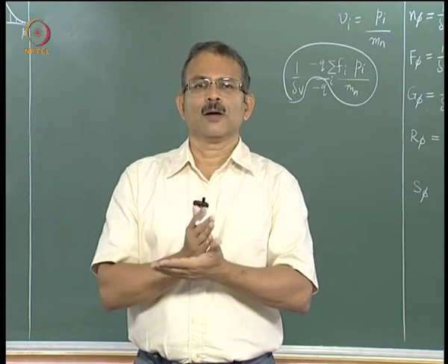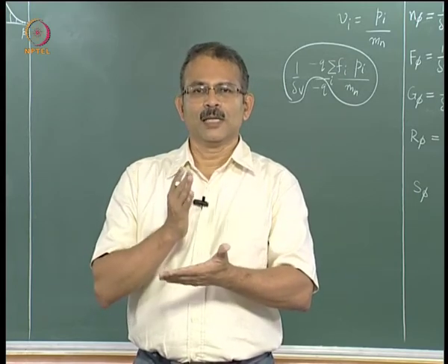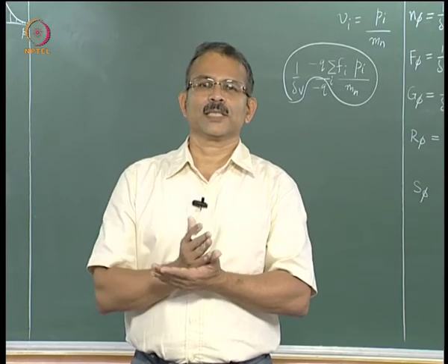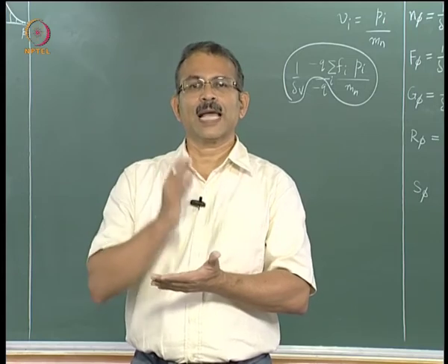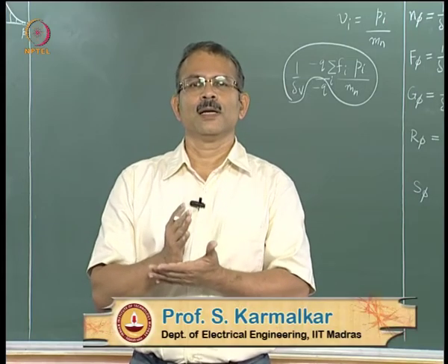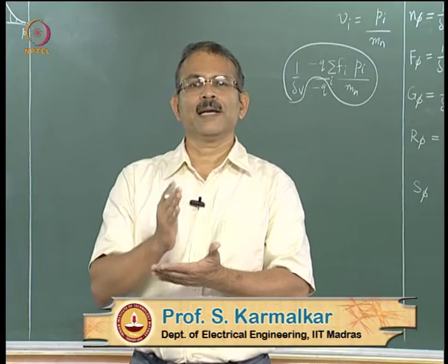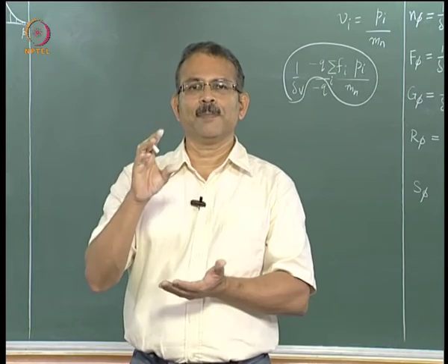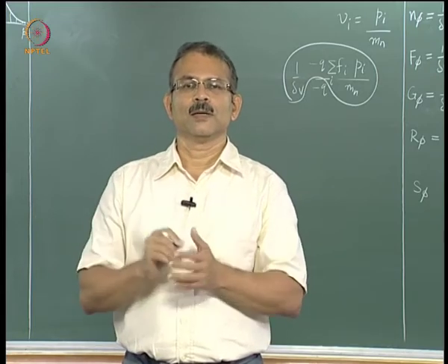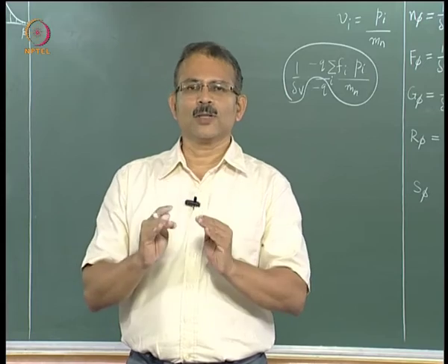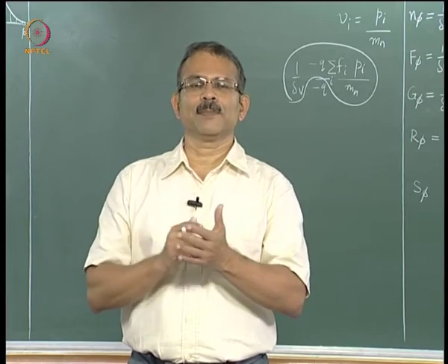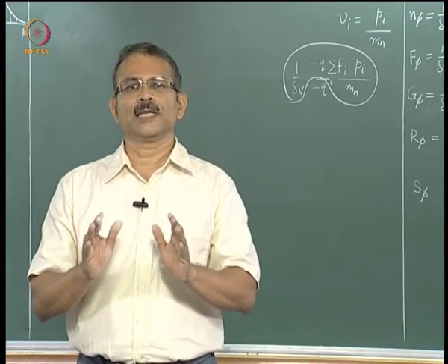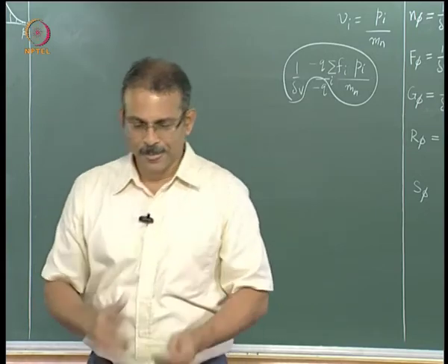So small p or lowercase p represents the momentum of a state. It also represents hole carrier concentration, right. On the other hand, capital P will be used for average momentum density. So small p is associated with an individual state, capital P is a property of an ensemble. Depending on the context, you can decide whether p represents momentum or carrier concentration, but capital P is momentum density of an ensemble.